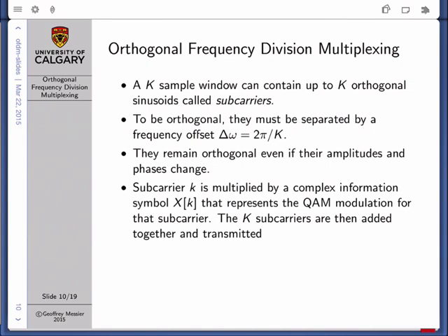And as long as we implement the cyclic prefix, once we sample our transmitted sinusoid at the receiver, every little piece of the transmitted sinusoid will experience only amplitude and phase distortion, which we can then remove with the one tap equalizer. So we have a communication system put together now.